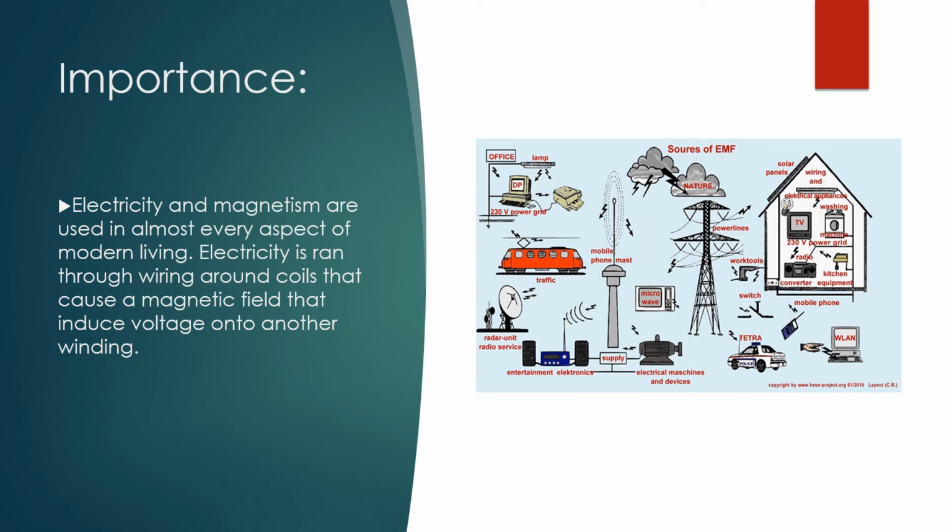loss on that voltage, because if they're producing 120 volts RMS, which is AC, alternating current, down a power line, when I get it out of my wall outlet at 60 hertz, 120 is what I'm looking for. But if I get it out of the wall outlet at 60 hertz, 100 volts RMS, some of my devices might not work all that well, because some devices use circuitry that is looking for quite possibly a knee voltage on a diode to allow current to travel through a path.